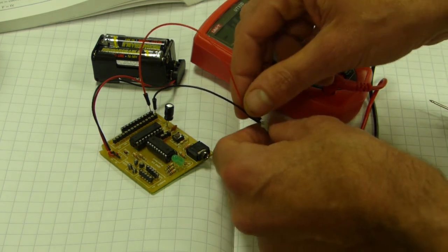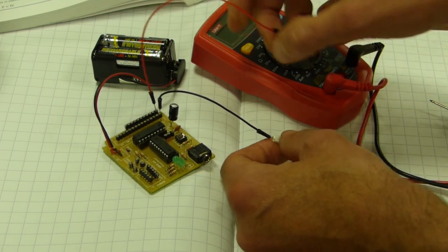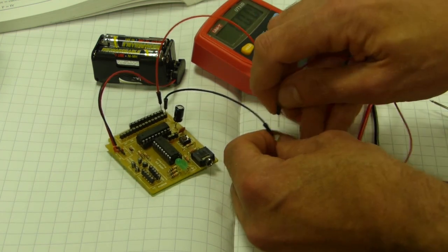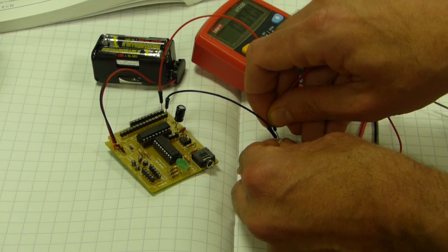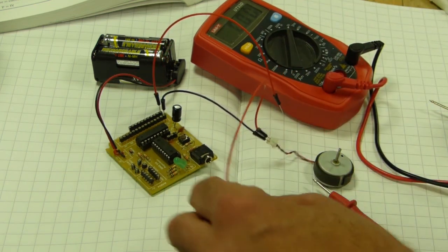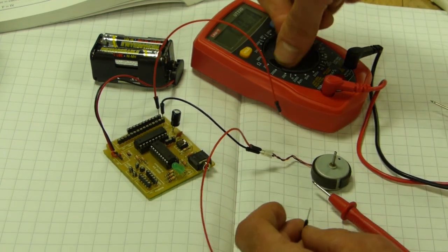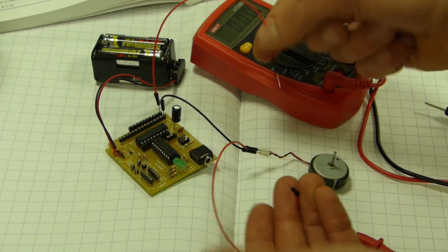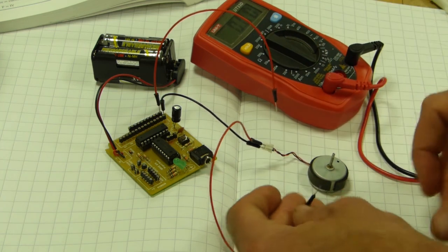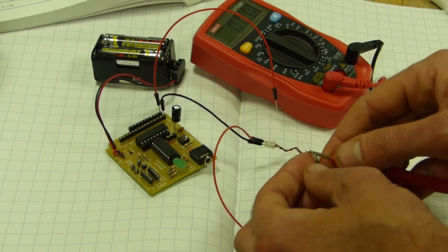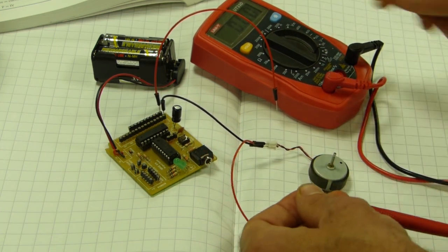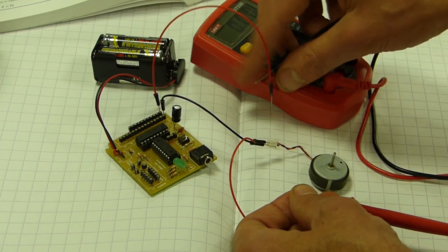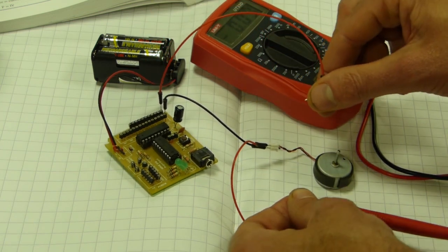So what we do, we'll just take one of these wires out, the positive in this case. We're going to add another jumper wire, like that. And now I'm going to switch this down to 10 amps. And you'll notice the motor, obviously I've broken the circuit like that, it's not working. But then when I hold the wire together, like this, oops, it works.